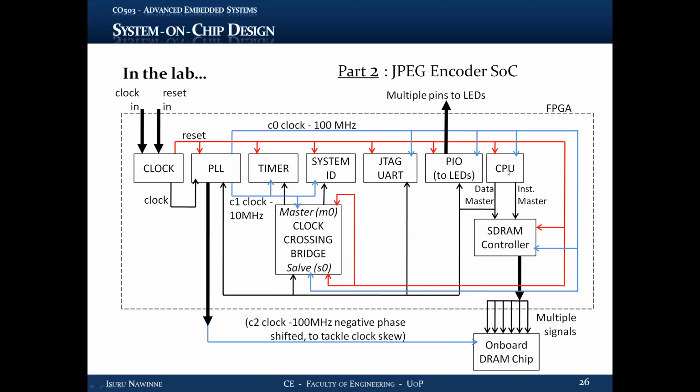So the rising edge that the CPU experiences and the same rising edge that the off-chip RAM experiences happen at two different times, because the signal gets delayed through the copper connection. That is clock skew. The same clock edge occurs at a delayed time for the off-chip device.